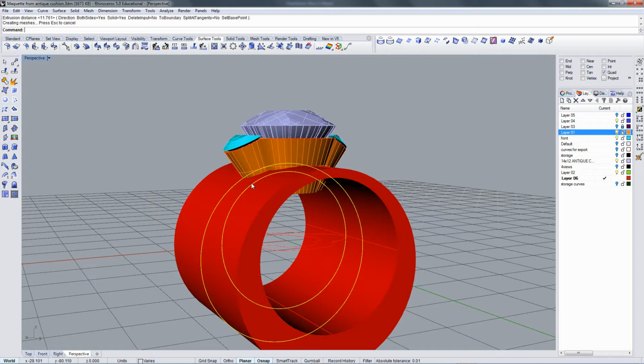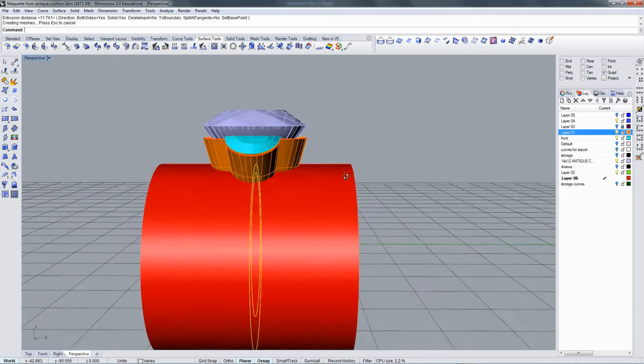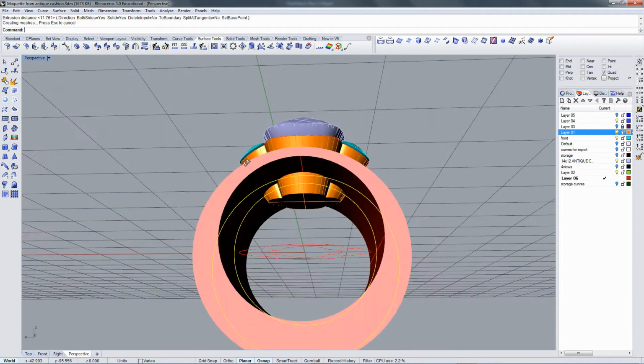But it's not 100%, guys. And you'll be modeling along and you'll make a mistake and you won't know why. So that's why I constantly, once again, the hygiene, I change the C-plane before I extrude so that I know I'm getting an exact extrusion.